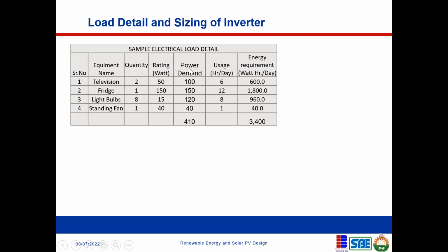And then with that information, you will be able to determine the peak demand or the peak power requirements of the system. And with that peak power requirement, you'll be able to size the inverter. It will be a wrong design if you size a system for example at 500, whereas the peak demand, the load at some point could get up to 700. What that means is that you have under-designed that system. So you need to know what the peak load would be so that you'll be able to size the inverter very well.